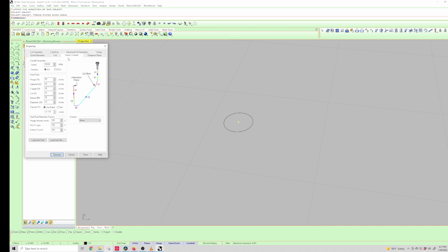Same deal. When I'm drilling out a hole but using engraving, you don't want to be spinning fast. You want to slow things way down, because you'll generate a lot of heat, and the bits just cut better when they're spinning slower, like a drill press. So I usually, if I'm drilling, I'm going to go down to 7,500. That feed rate's good.